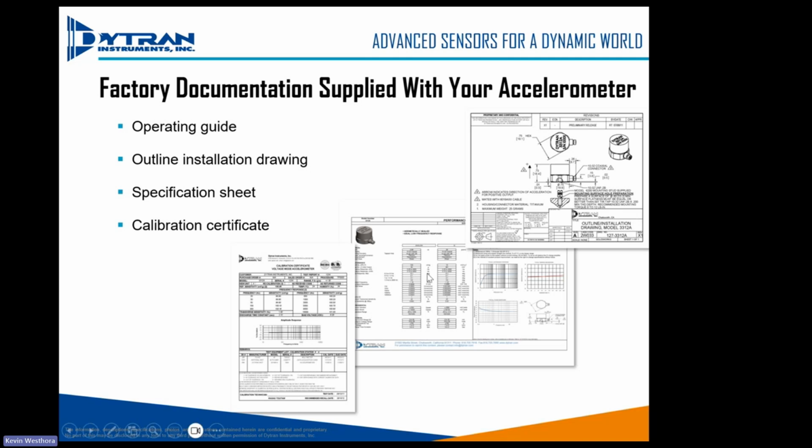In the middle here is our data sheet or specification sheet. So all of the pertinent information of your sensor is listed here, from the weight to the sensitivity to the G range to the frequency to the noise, temperature, whether it's isolated or not, whether it has a connector, how to mount it, etc. And then there are three typical plots of data that we provide you. The first one here is the low end roll off, the AC coupling of that sensor. The other is the typical temperature deviation. And then the last one is typical phase of a particular accelerometer. So very important data sheet that you can find on the website.